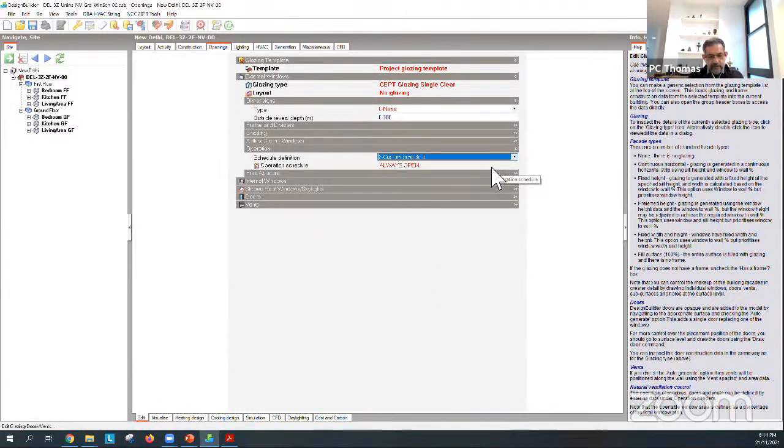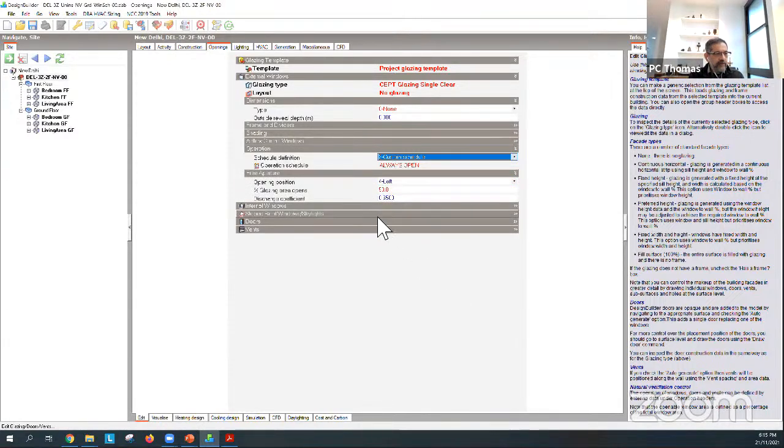So initially I'm just going to do a run where the windows are open all the time, okay? And you can then control how much of the window is open. Is it 5%? Is it 10%? Is it 50%? Half of the window? You can never get 100%. Okay, so 85%. If you've got windows that open fully, from the frame about 85, 90% you may get. 100% you don't. Okay. So here I've said 50% of the window opens.